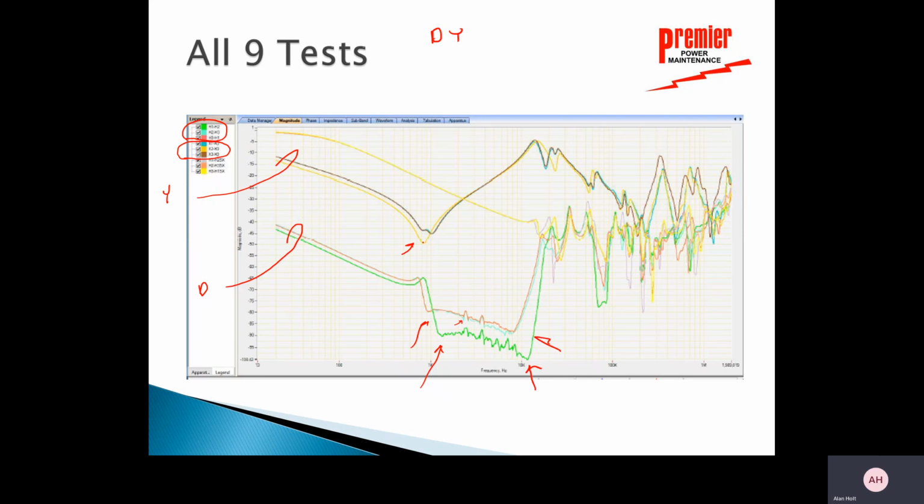I only see the one dip there instead of the two like I saw for the Delta. But again, I see two traces basically right on top of each other. I see a little separation of the darker blue there, but basically they're on top of each other. But that middle winding is a little bit off, but the resonant frequency is pretty close on those.